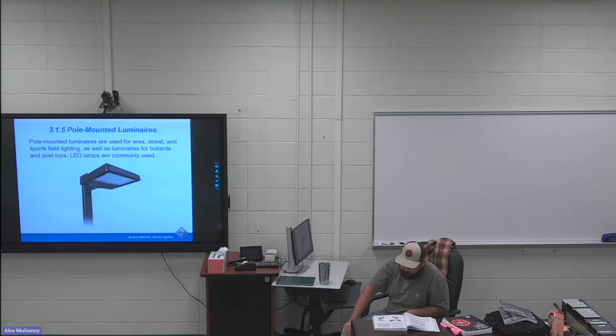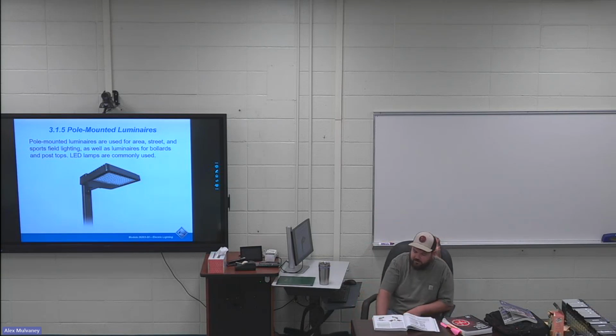But my highlight for surface mounted luminaires is on page 31. That last paragraph, second sentence is highlighted. When mounting luminaires that weigh more than 50 pounds on a ceiling, NEC section 314.27(A)(2) requires that the luminaire be supported independently of the box unless the outlet box is listed for not less than the weight to be supported.